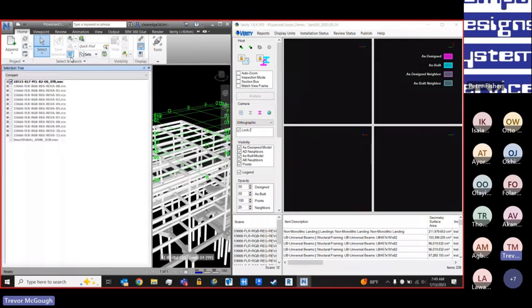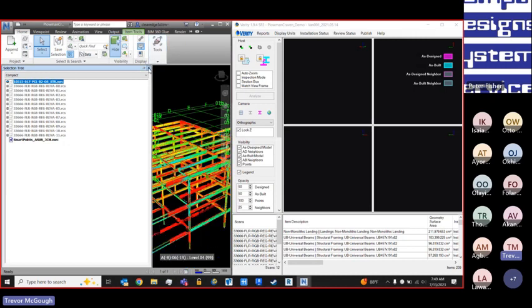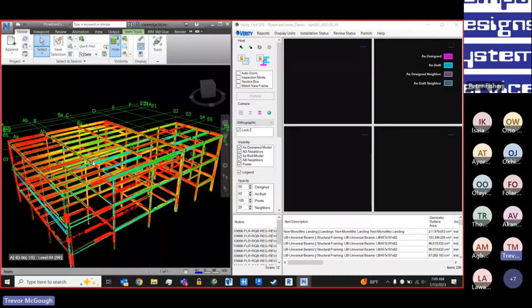And so that way we can then take that point cloud, bring it back into like Revit or AutoCAD, and then say, hey, this is everything that's out of tolerance. Can you please update this? So there you can see over here on the left, here's an example of a heat map based upon like a 3 centimeter deviation. So again, that way it trims the point cloud down and makes it more intelligent. So that way I can show as-built deviations quickly like that. And that right there basically wraps up a quick overview of the Verity application.